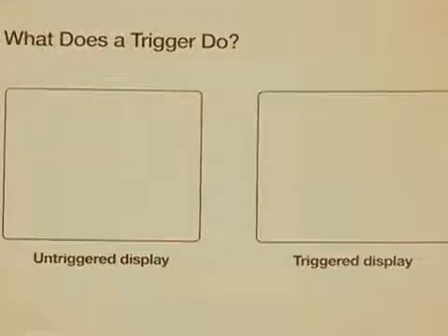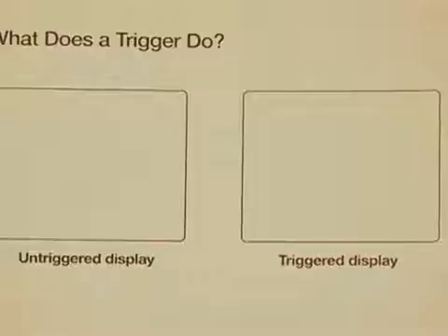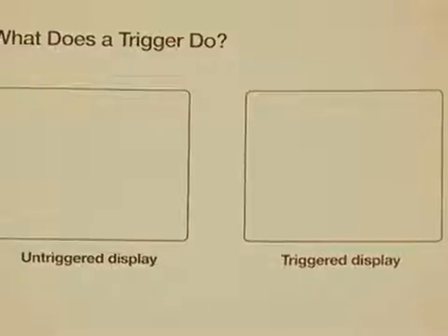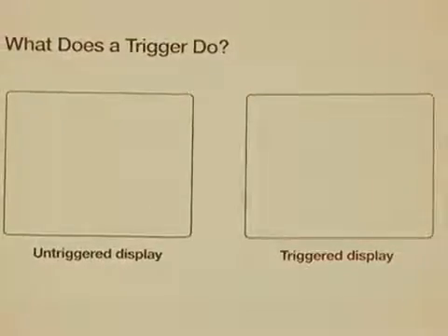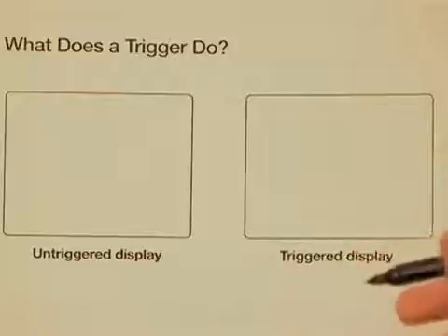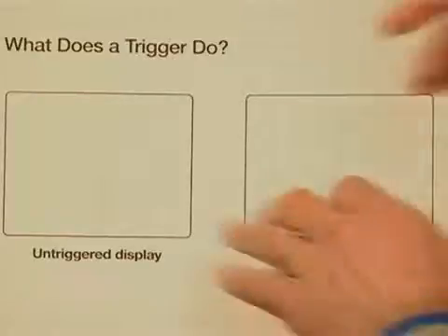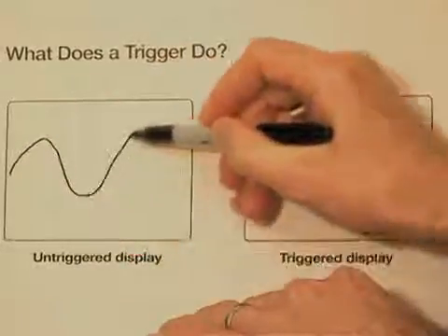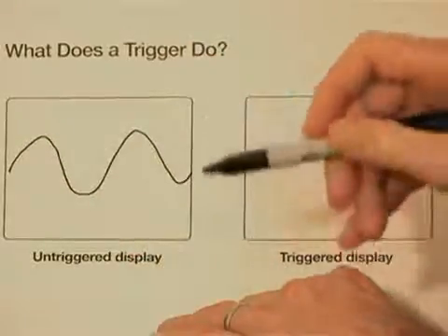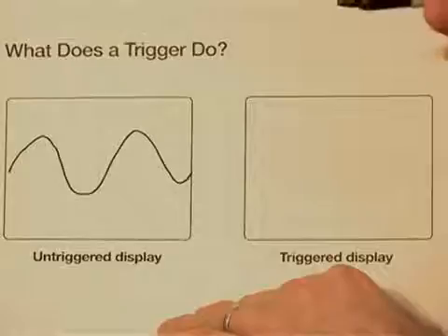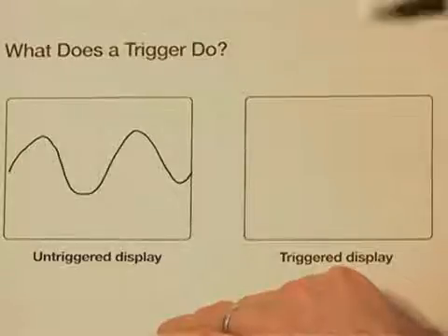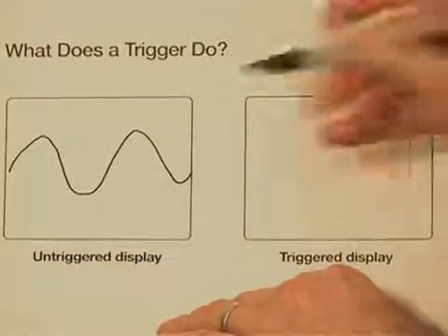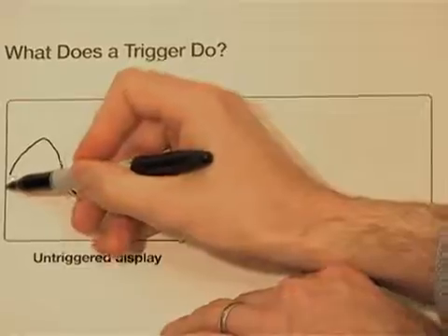And the reason it's important to set that correctly is without triggering, your scope just updates its data at arbitrary times, and your signal is repeating at arbitrary times, and those probably won't line up. So, for example, imagine that your signal looks like this, and that's what it looked like the first time the scope happened to update, and then the next time it was time for the scope to update, it happened to catch the signal a little earlier.